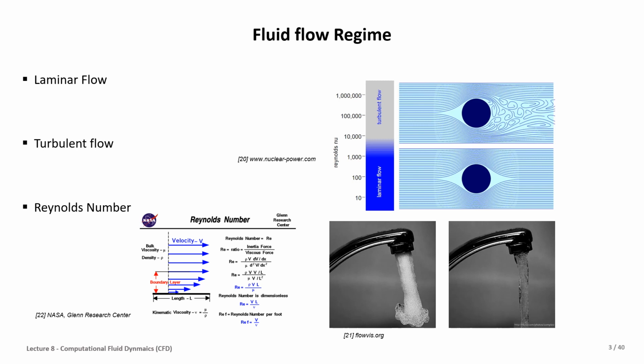But when we look at the turbulent flow, after the object there are a wake and complex streamlines, which come from the von Karman street. For different Reynolds numbers, they behave differently in size and continuity, and this is one of the different visualizations of turbulent and laminar flow.